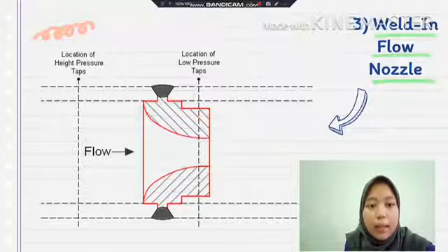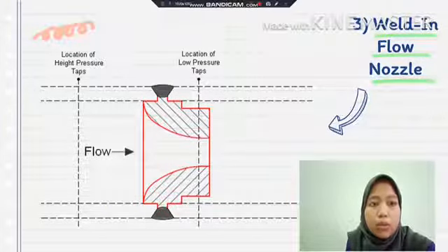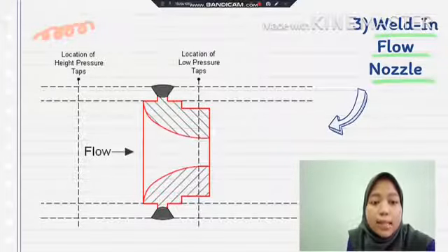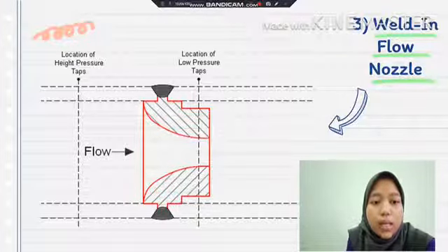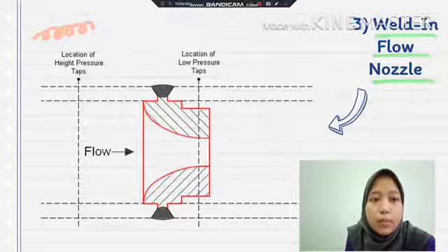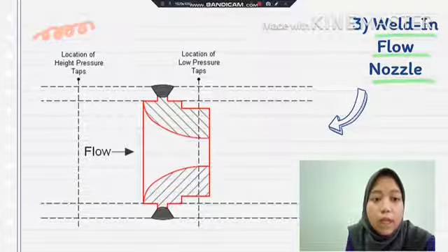Other than that, pipe wall pressure taps are used with this nozzle design, and it is available in complete flow metering section. For special application or for the smaller line size, weld-in flow nozzle with integral metering taps are provided. These flow nozzle designs may include a short section of upstream and downstream pipe with flange, bevel or socket weld ends.